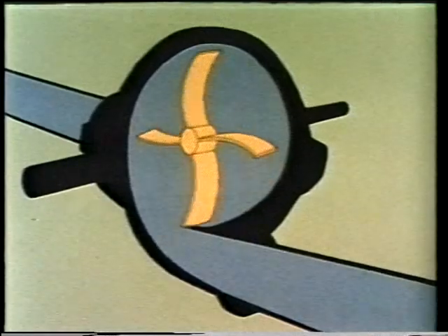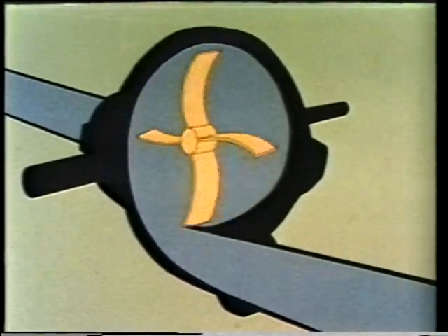Sometimes vibration occurs because of a condition that's unique to a specific piece of equipment. For example, if there's contact between a rotating component and a stationary component in a machine, there may be a specific vibration associated only with that particular contact. Pumps can also experience vibration caused by cavitation. Cavitation, that is, the formation and collapse of vapor bubbles in a pump, can also damage rotating components in different ways.